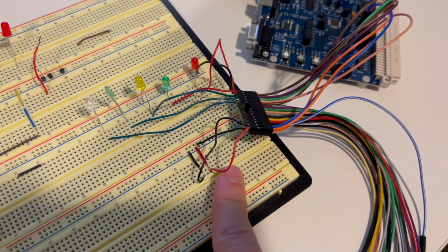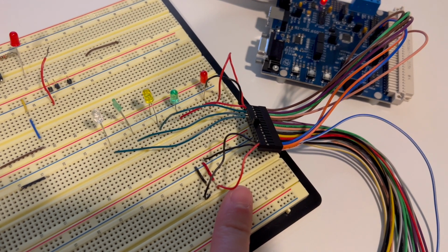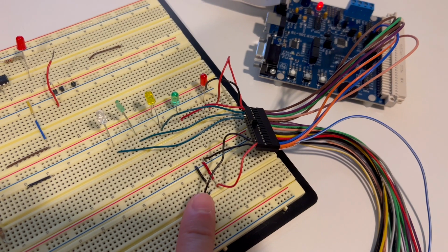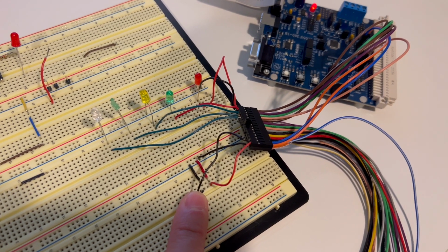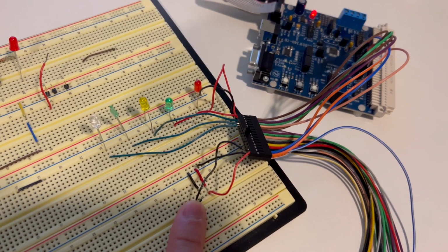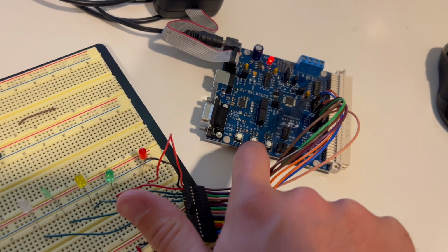All right, here's the operation of the circuit. Right here is this red wire, and that is for the startup, which is connected to input P2.2. Then this black wire is for the select destination, which is connected to P2.1. And then finally, there's P2.0, which is for insert dollars.